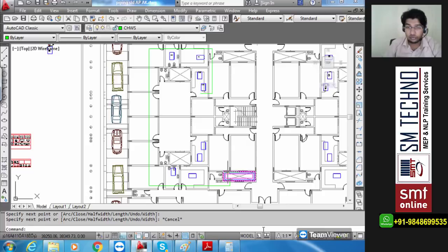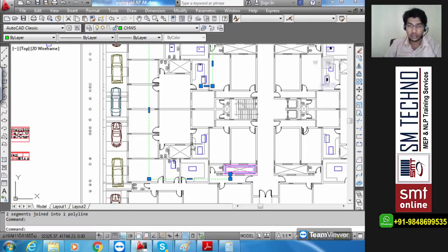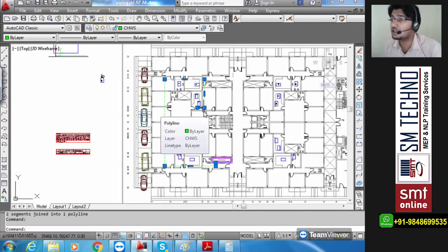All right. So from here you can see if I'm going to select this, it is a total polyline from there, and because we had to break that here, I'll try to join those. And the whole thing is selected at once so that it will become easy for me to take the offset. Why am I going to take the offset? For the return. I don't want to keep tracing the return again at the same level, and maybe I will not get exactly 300 mm.